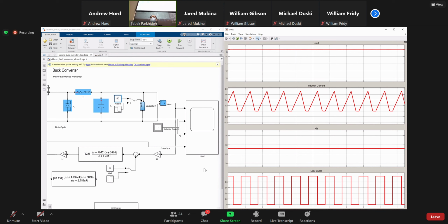So why is this important? This is important because your power supply can have different load profiles, right? And may need to operate at no load conditions. What you see here, at no load or low load conditions, the performance or characteristic of this converter is very different than nominal power. So therefore, in converters, one thing that you should be careful about or need to provide as a spec is the boundary condition.